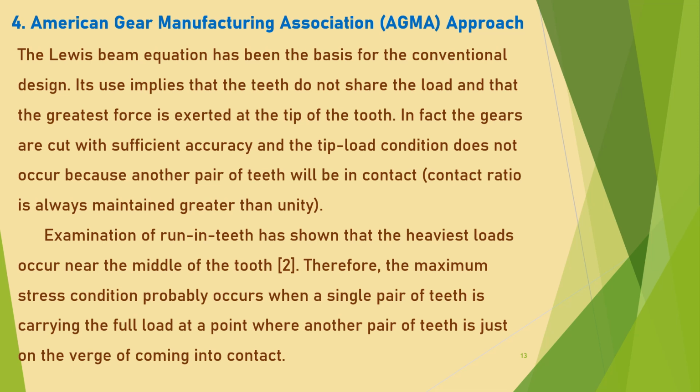You must have read in the theory of machines that the contact ratio is always maintained greater than unity. Examination of run-in teeth has shown that the heaviest loads occur near the middle of the tooth. Therefore, the maximum stress condition probably occurs when a single pair of teeth is carrying the full load at a point where another pair of teeth is just on the verge of coming into contact.